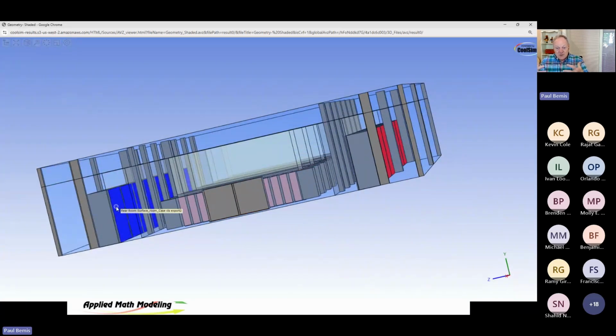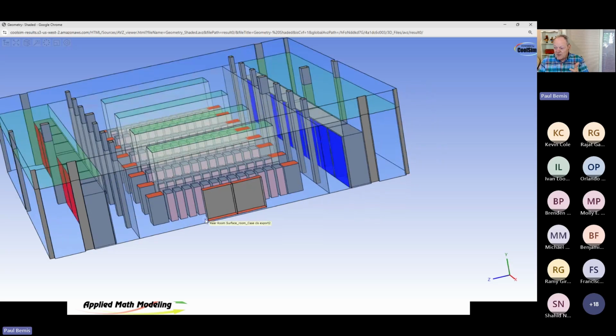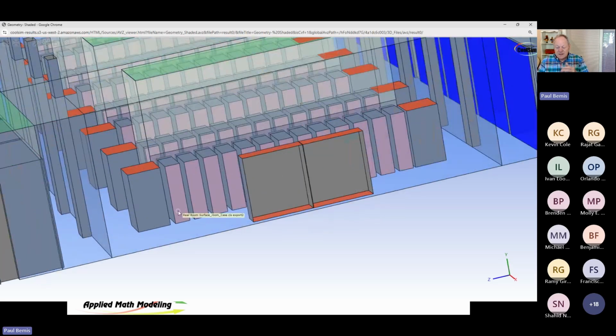Now, basically what's happened is as the rack appetite for air goes up, remember that it generally wants about 125 cubic feet per minute per kW. Rule of thumb, right? Use 100 if you want to do easy math in your head, 100 CFM per kW. That assumes a delta T on the rack of about 30, 35 degrees. Now, what happens is if you have racks like these that are running at very, very high loads, I'm seeing racks now in the range of 40 kW, and I'm being told it's going to go to a megawatt.